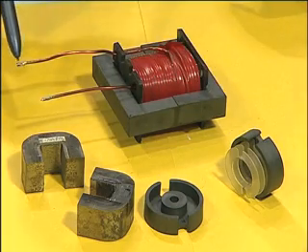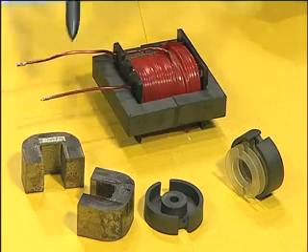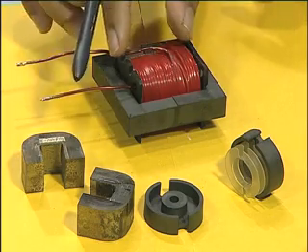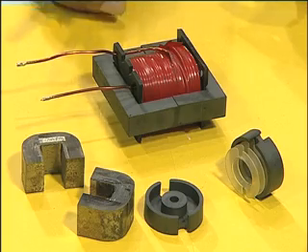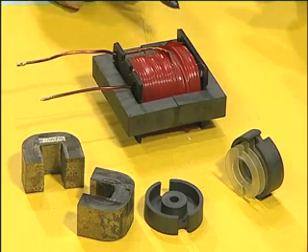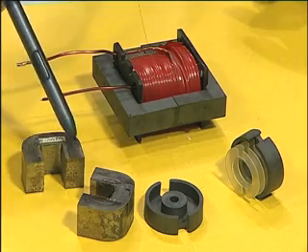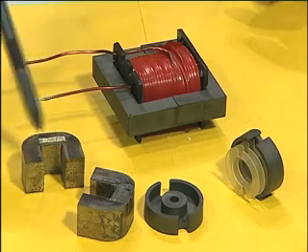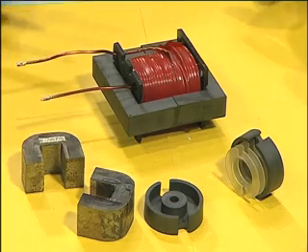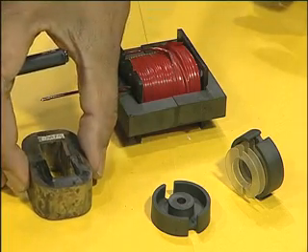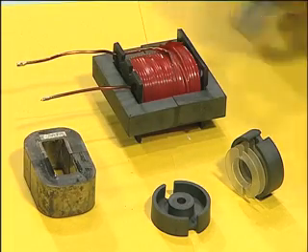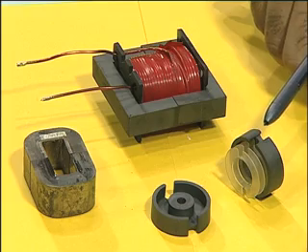Okay. You have one end of the winding here, another end of the winding here, goes through this coil, there is a bobbin, this bobbin is fitted into the core, which is a ferrite EE core. You can also have different types of cores. This is a metglass type of core, this is called a CC core, going by the geometry. This is another ferrite core called the pot core.